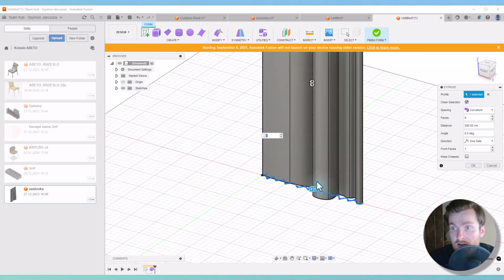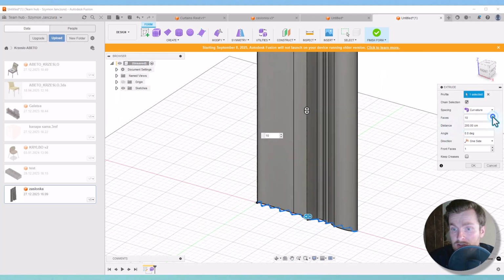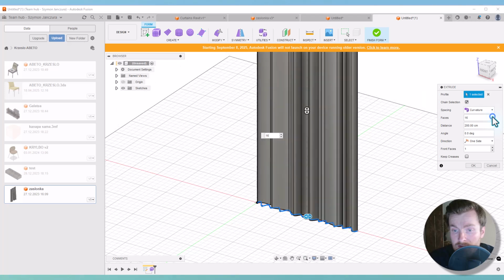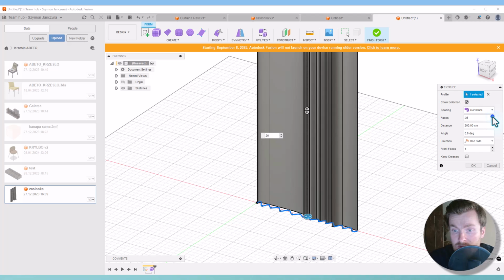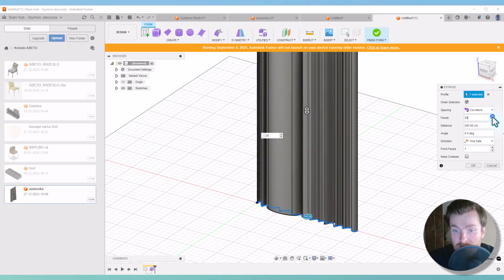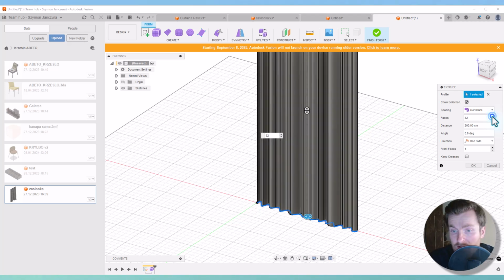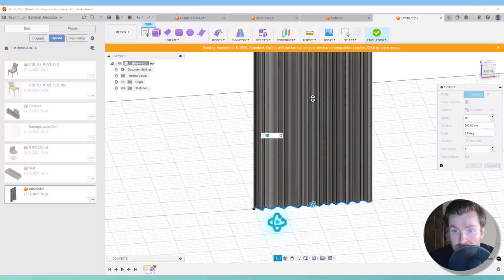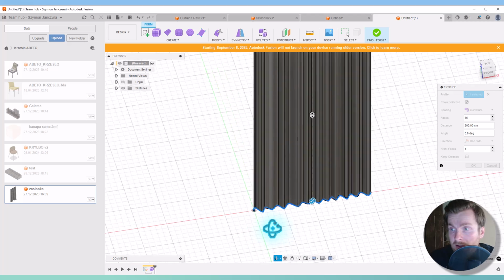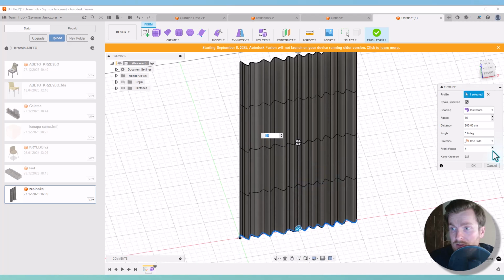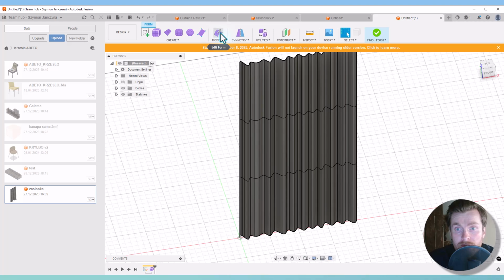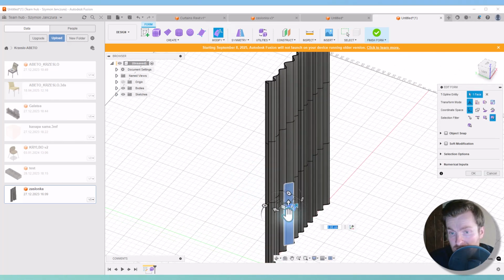Now it's good to have more than 8 faces here, so I will adjust the number of that until it matches the shape I defined. Okay, it looks pretty good. And I will also add some horizontal divisions. Okay, maybe 3 actually is enough. The height is 200 centimeters, so this is what I want. And I click OK. Then I have all these modifications tools, so I have each line, each face that I